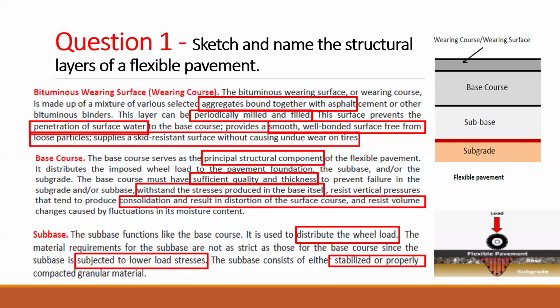Okay, so because of this, the way that we are going to do design is different in the flexible pavement and also in the rigid pavement. In the rigid pavements, the load is distributed due to the flexural bending, but here it's transferring grain to grain. Any question?